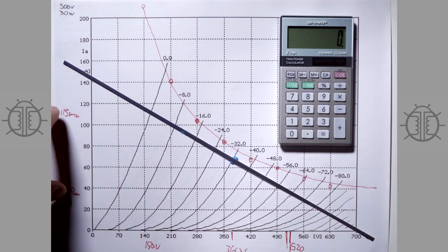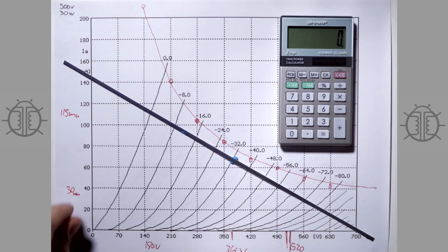And then we do the peak-to-peak current swing, and we divide that by 2.83 to get the RMS current swing. And we multiply those together, and that gives us a ballpark of the power we can expect from this Class A single-ended output stage. And so I'll do that really quick so we can see what that is.